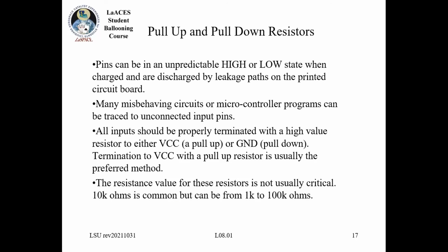So I could start interfering with signals, but that really only becomes a concern when you're talking about very rapid signals, like megahertz speed communications. Or it could potentially be the case that you just have a lot of different things connected to that pin. So that also could cause that time constant.